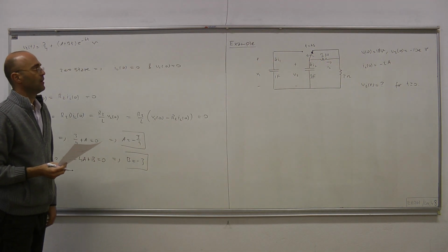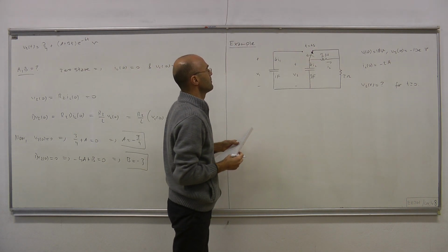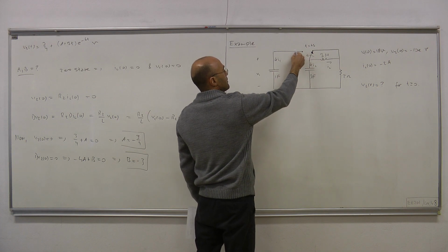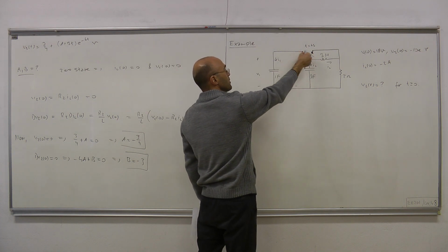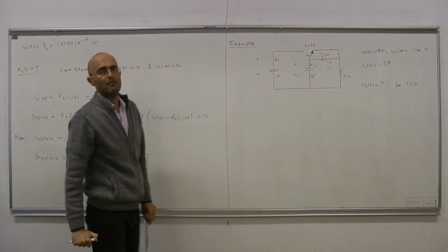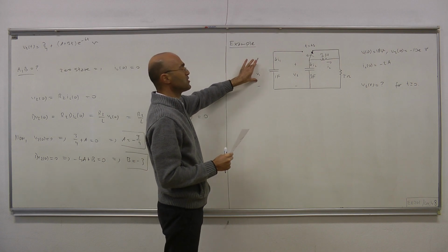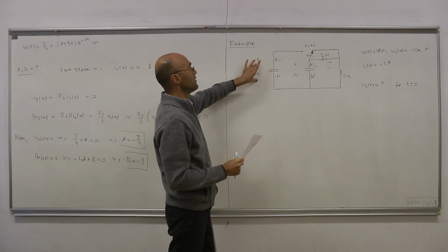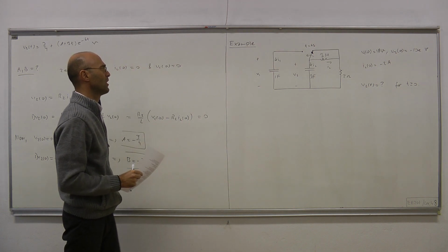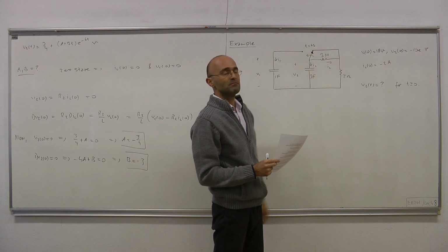Okay. Now, initially, it switches in that location, so that tells us the following. First of all, the current here is 0 because this is open circuit. The current through the capacitor is 0. That means rate of change of voltage is 0. That means voltage remains V1 constant until the switch changes position. What else? IL is short circuited initially.